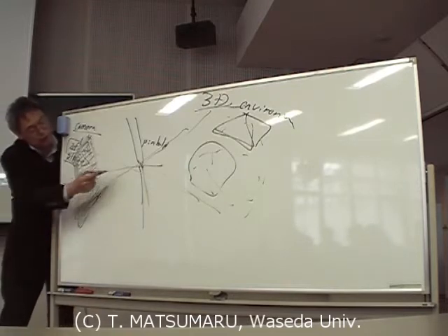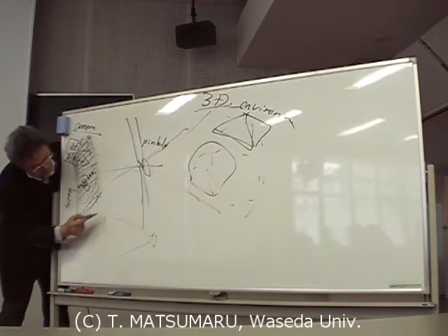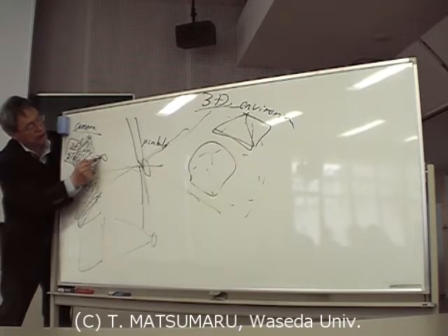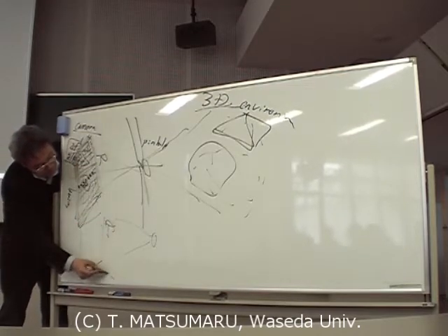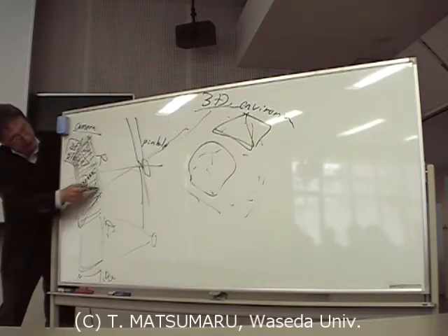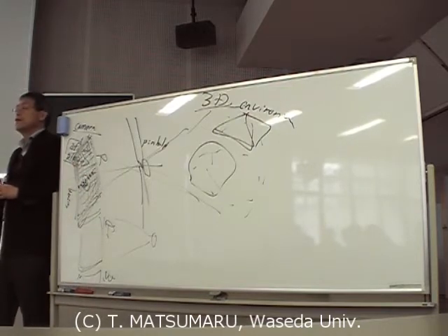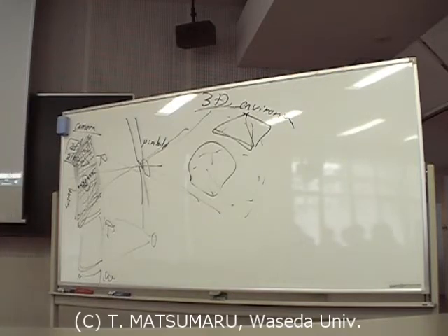This is a monocular camera, but by using color filtering, three filters are used in each two-dimensional image. For example, the red part, green part, and blue part are detected, and by combining these three two-dimensional images, the color is understood. And the stereo camera is also here. The three-dimensional environment is projected onto the left-side camera's two-dimensional plane and the right-side camera's two-dimensional plane. It is projected here.